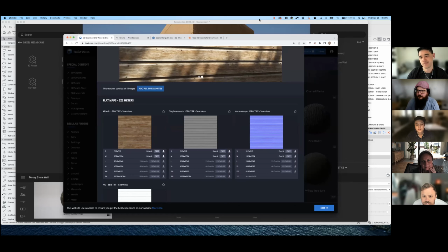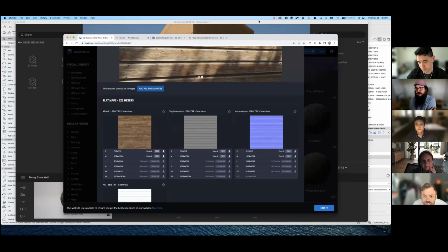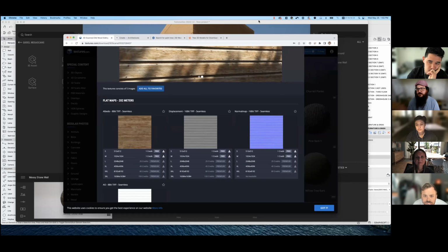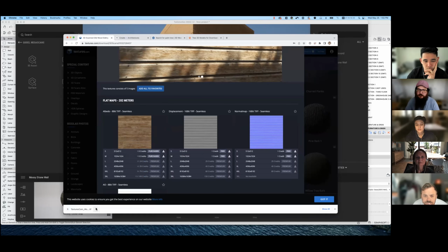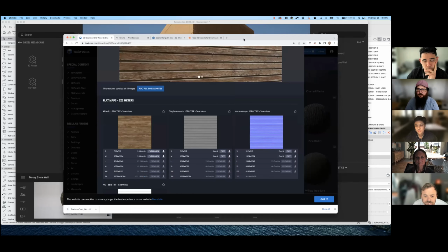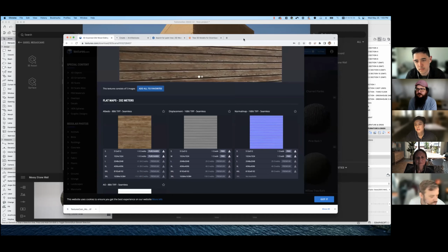If they're coming into Archicad before Twinmotion, which is oftentimes a workflow that we use because we want the Archicad model to have some similarity to the Twinmotion renderings, there are rules of thumb for that. JPEGs and PNGs shouldn't be more than 2 or 3 megs. Regardless of their resolution, they should be under 3 megs max if they're coming into Archicad. I think Twinmotion's a little bit more forgiving, but it really depends on how much of the model is covered in that surface.